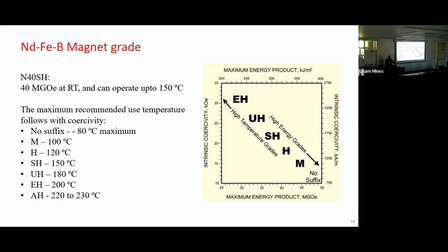It's actually not that bad. It is simple dilution of your moment. You add 4%, 8%, even 10%. You're losing that much magnetization, and then the overall energy product is your magnetization squared. So if you lose 10%, effectively you're losing 20% of your energy product.